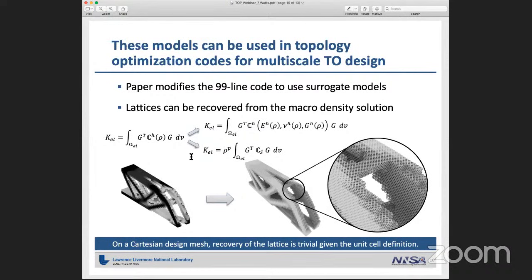I won't get into the details, but basically instead of doing an interpolation of a solid isotropic elasticity tensor, you generate your own based on these models. That's really the only difference. Everything else in the optimization remains precisely the same.